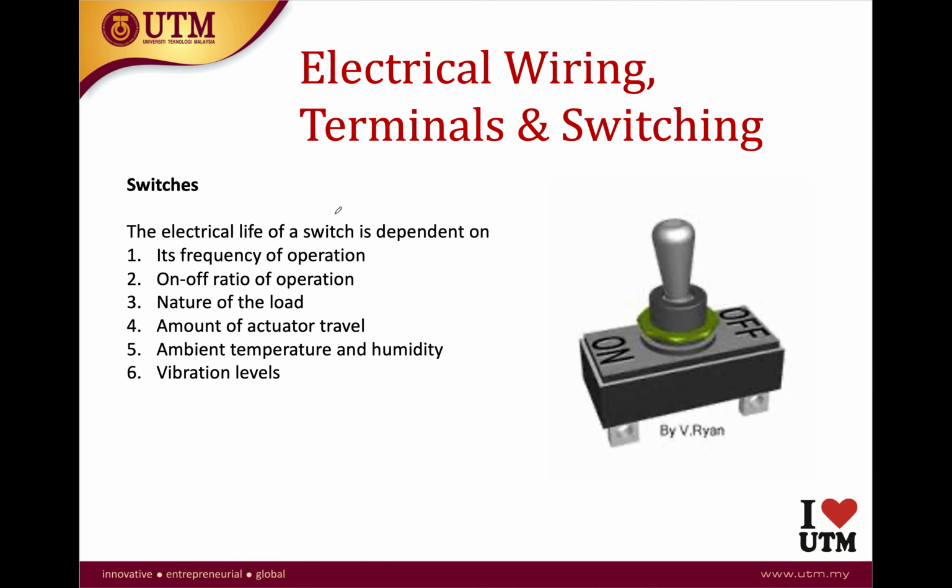The electrical life of the switch is dependent on the frequency of operation, the on-off ratio of operation, the nature of the load, the amount of actuator travel, ambient temperature and humidity, and most importantly, the vibration level.